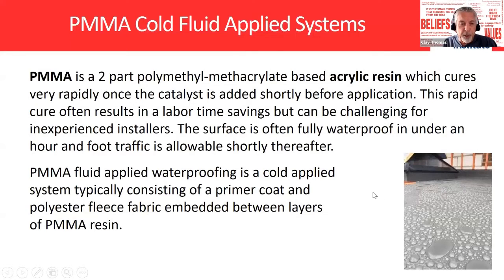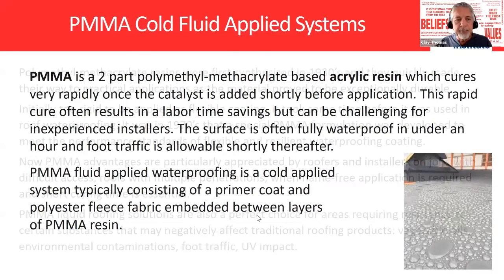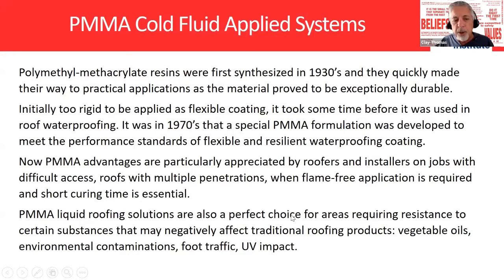PMMA fluid applied waterproofing is a cold applied system typically consisting of a primer coat and polyester fabric embedded between layers of PMMA resin. One of the key components of this, as Glenn mentioned, is quick cure time. If I'm doing a parking garage and I have to stop traffic, I want to use one of these products so I can drive on it again within a few hours.